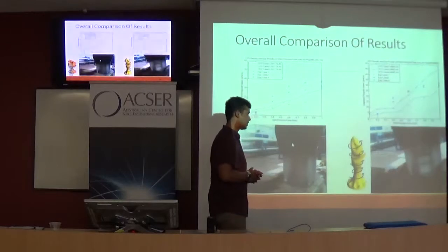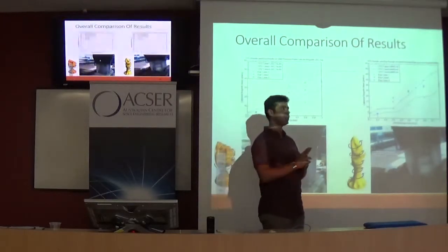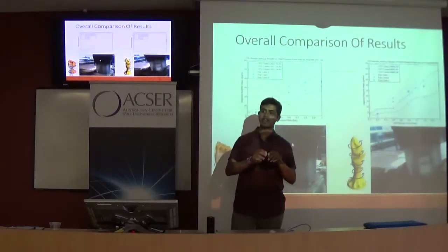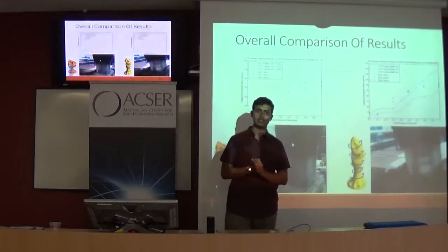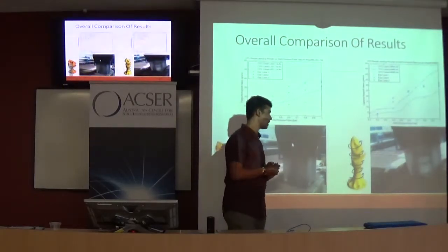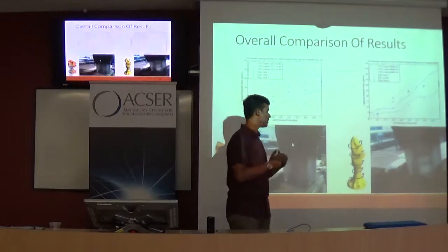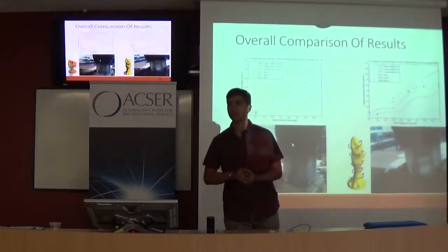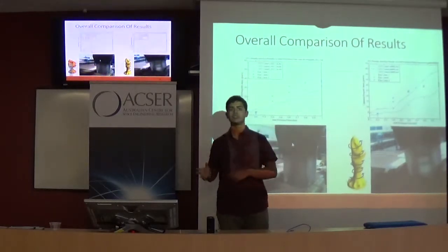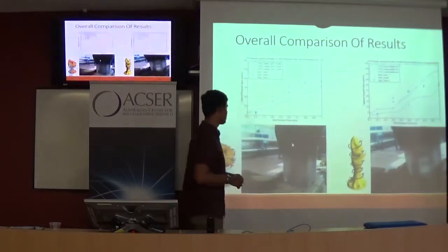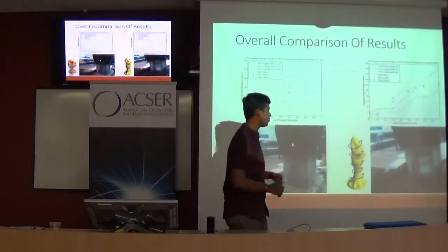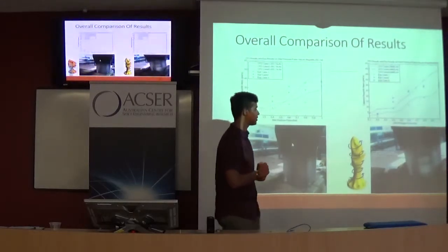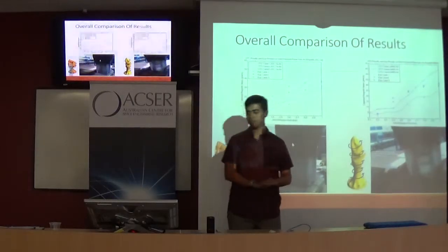Given that this could have been done in a much better way, where one can use PIV techniques, non-interference techniques, to photograph regolith as it is passing through gas, that could be one piece of work that could be taken up to better gauge this. So my experimental validation was on the basis of the collection of the regolith. Another important thing that can be done is looking at the distribution of regolith, how it is taking place. I was able to get some photographs and compare them with my CFD model and say that this is what the flow looks like in the model, and this is what one is getting from the experiments.